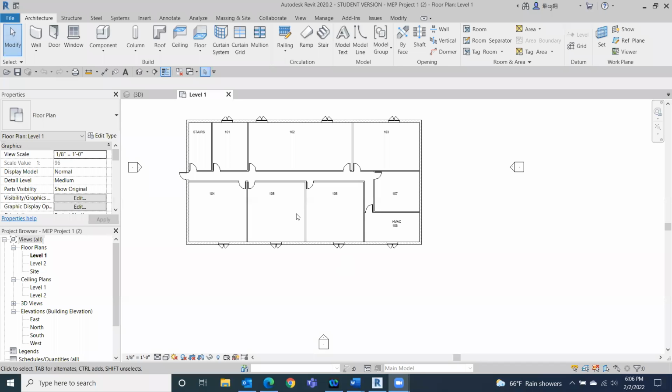It sounded like when you texted me earlier, you were having some issues with the mechanical template as well, but you were able to solve that. I figured that out by going underneath the modify button on the top left of the screen, clicking the down arrow, and selecting underlay elements, which was not clicked. All I did was select that box, and it allowed me to go back to Revit as I know it. So everything's fine with that now. Okay, great. Yeah, that was strange.